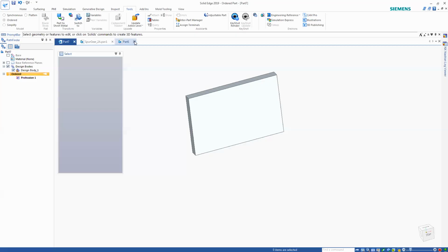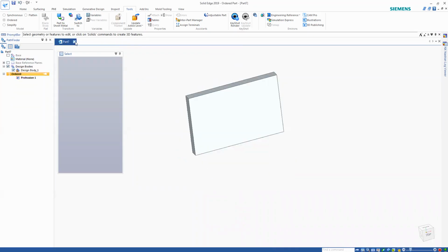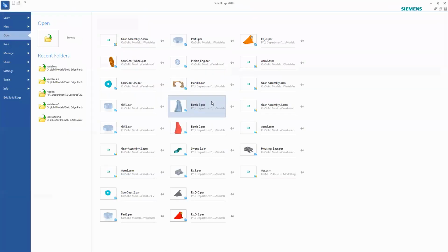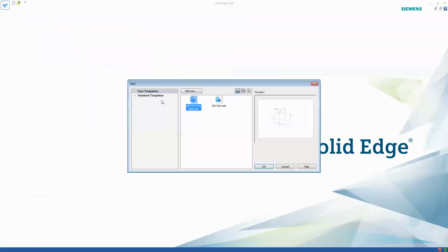Okay, I'll show you all these things. So let me close this. I don't want to save it. We'll see whether we can get some parts already. Say new, and remember, this is the part 5 template. I don't have a template created for the assembly file, so I open the standard templates. I go to metric, then ISO metric assembly, and then I say okay.